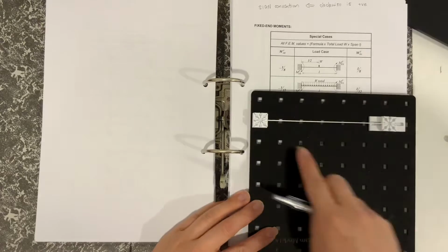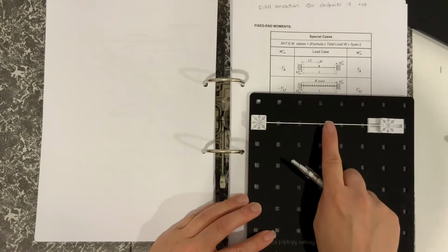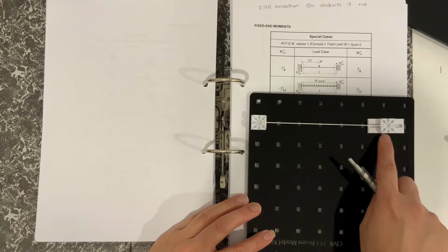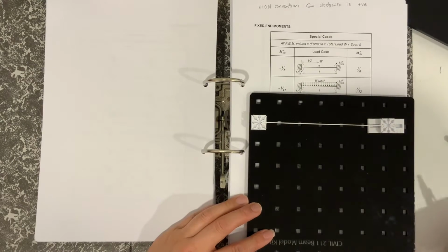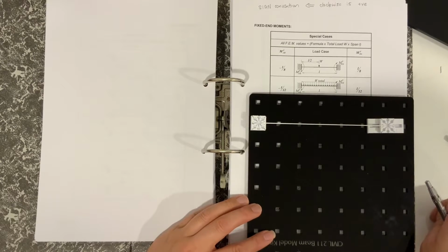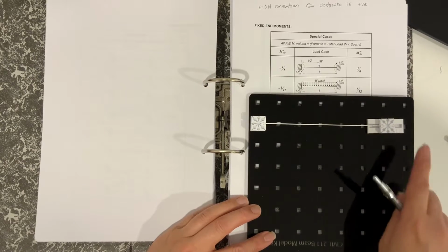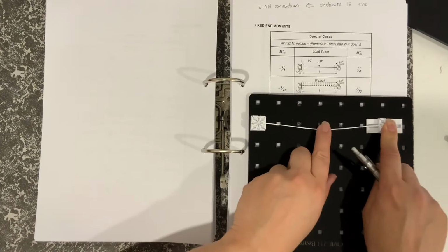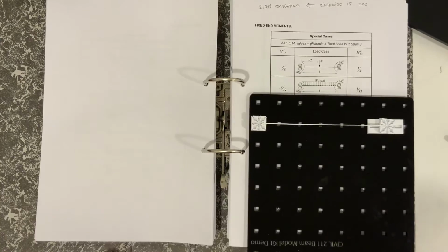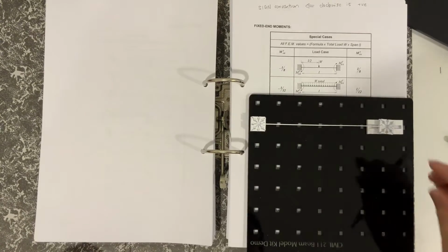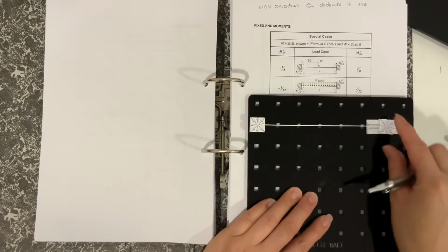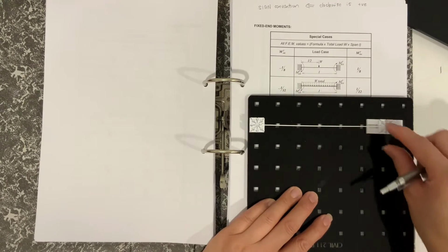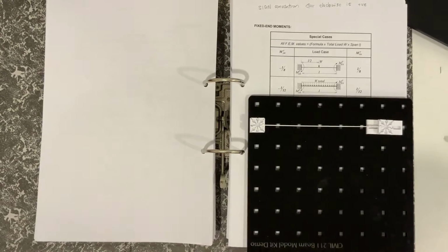So here is one end fixed, and one end is also fixed. Technically speaking, it should also be on a roller, so you don't get the chain effect or the catenary reaction effect. If you don't know what catenary reaction is or chain, just Google and you'll see that it's when that end's fixed in it. It provides some extra other restraint which we don't want to include. So you'll see it like that, but what it really means is that it's free to move in that direction here, but not free to move in the other directions.